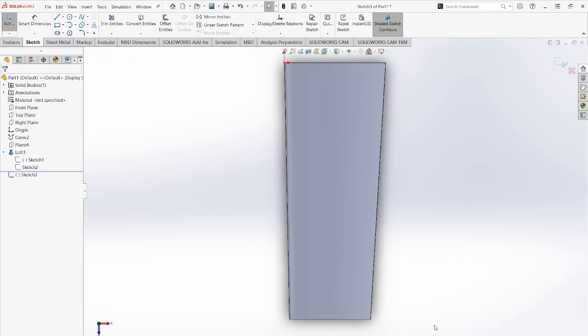In this case, our aileron is going to extend from the tip up until 1 inch before the root, and it's going to be 30% of the mean aerodynamic chord, which in this case is going to be a cut in of 3.24 inches.